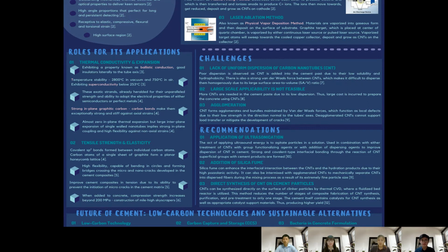Next, to tackle the problem of poor dispersion, silica fume is added to enhance the interfacial interaction between CNTs and hydration products due to their high pozzolanic activity. The pozzolanic activity is a measure for the degree of reaction over time. Additionally, silica fume could be intermixed with agglomerated CNTs to mechanically separate CNTs into dispersed fibers to further improve its dispersion. To lower the cost, it is recommended to apply direct synthesis of CNT on cement particles.